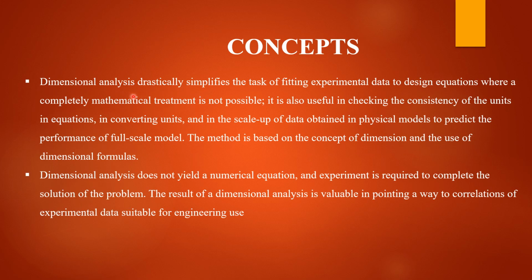Let's look at the concepts. Dimensional analysis drastically simplifies the task of fitting experimental data to design equations where a completely mathematical treatment is not possible. It is also useful in checking the consistency of the units in an equation, in converting units, and in the scale up of data obtained in a physical model to predict the performance of the full-scale model.